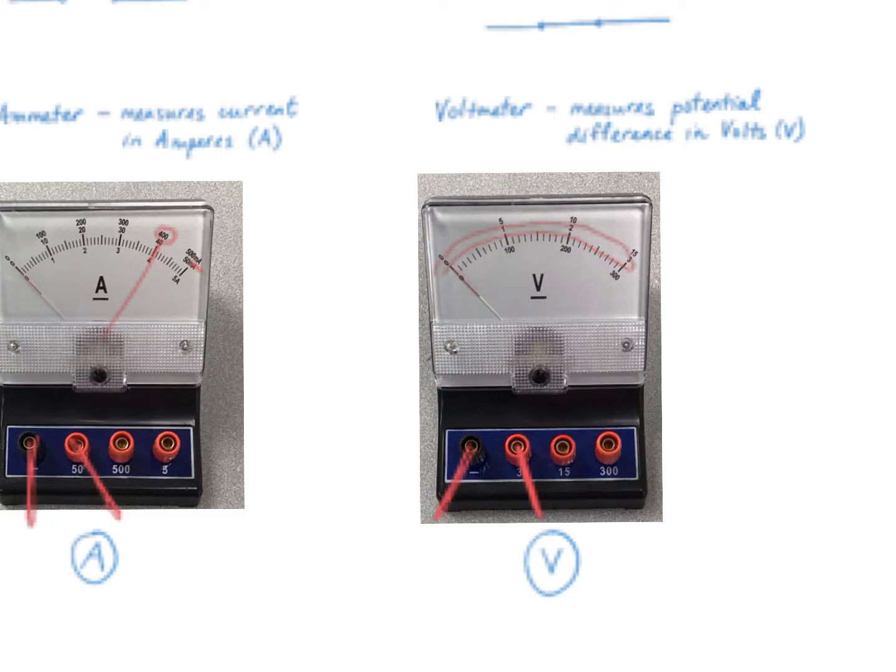Okay, so you'll see that this line here is 0, this line is 1, this line is 2, and this line up here is 3 volts. So if you've plugged your wire into one of these, then you have to read a different scale. But for us, we're going to plug into the 3, and so we'll be reading the middle set of numbers there. Okay, and that's where you are reading the voltage.